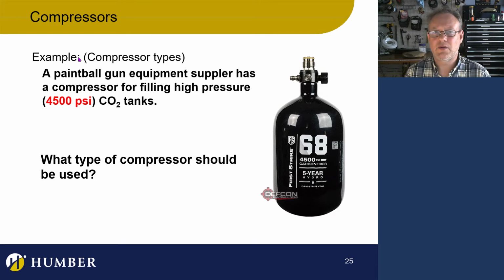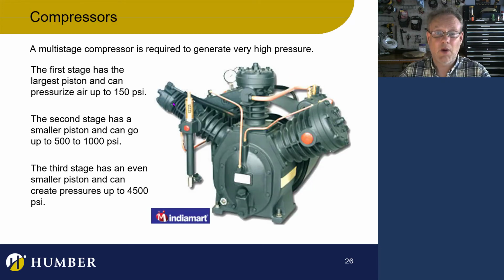Now, the other thing is that this is another compressor application, and it's really cool. In this situation, we want a really, really low flow rate, but extraordinarily high pressure. What do we do about that? For instance, these guys, like 4,500 PSI, ridiculous. I've done some work with these, and I've designed some of my medical devices with this technology. It's quite remarkable. We use a 3-piston compressor. This one has a really fat piston, the next one has a smaller piston, and there's an intercooler in between.